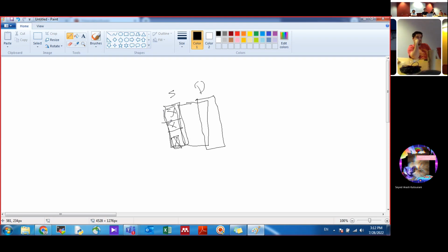Like I said, for an LDO, for example, your transistor will pass milliamps of current. It's better to put your vias here so all the current will flow. So what I understand from what you're saying is if you have the space, you're better to use a lot of vias. And if you're really short on space, you just do the minimum vias that you could have while putting the same voltage on all of the transistor.